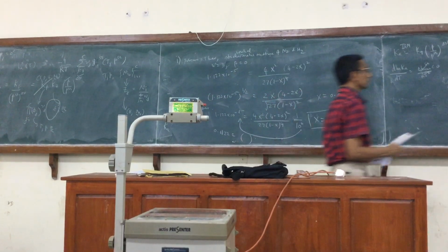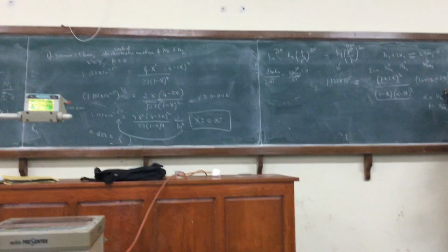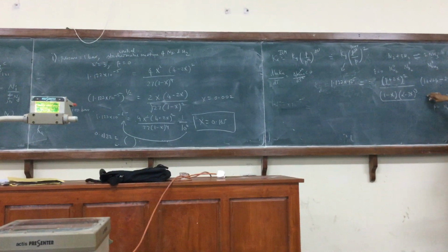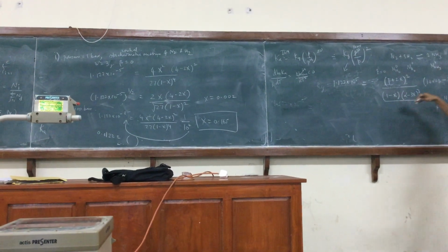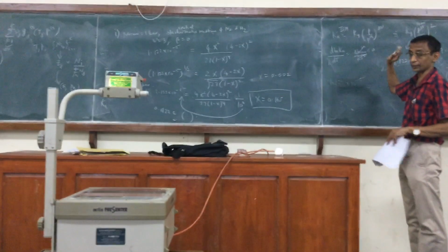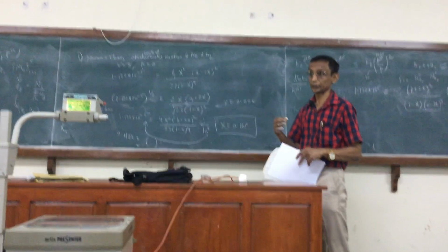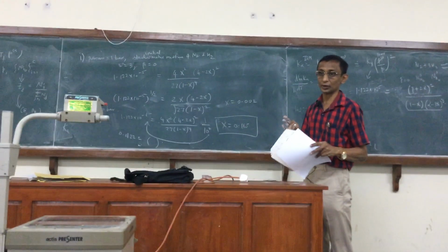So here you can clearly see that the general expression has to do with Ky. That is what you have to calculate, because Ky is what is going to give the equilibrium conversion. So that is how you are to interpret the other part of the Le Chatelier principle with respect to pressure, because Ka we know is a function of temperature alone.